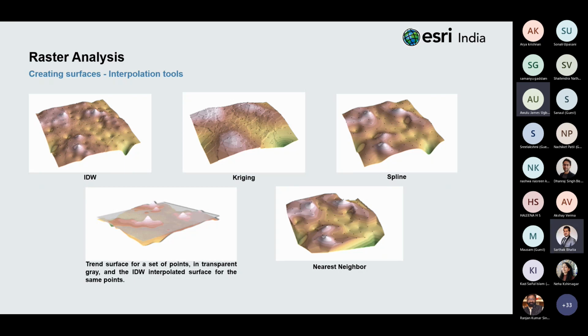Nearest neighbor or natural neighbors, as it is also known, is interpolation similar to the IDW interpolation, except that the data points used to interpolate the surface values for each cell are identified and then weighted using the Delaunay triangulation. So that Delaunay triangulation works on the same laws of triangulated irregular network. Now, natural neighbors or nearest neighbor interpolation reliably works when a much larger data set is used for the interpolation methods. It works on much larger data sets more accurately.